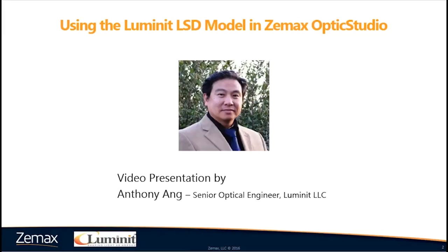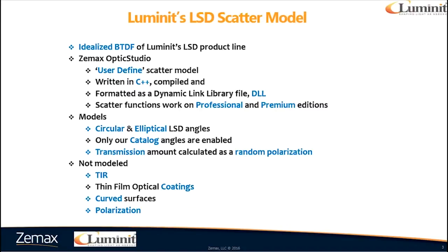Hello, my name is Anthony Ang, and I'm a senior optical engineer at Luminit. Luminit's LSD scatter model is the idealized scatter BTDF of our product line. In Zemax OpticStudio, the user-defined scatter function is written in C++, compiled, and formatted as a DLL file. Scatter as a function is available only on professional and premium editions of Zemax.